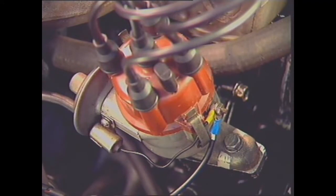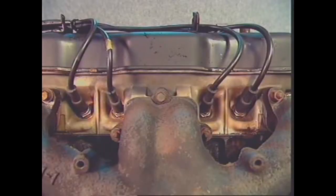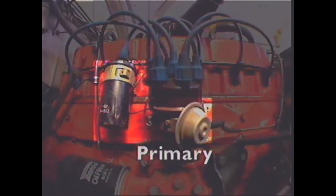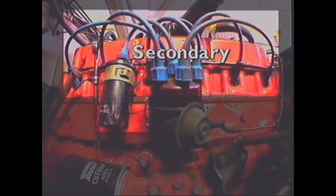a distributor, to house the contact breaker and distribute the high-tension voltage from the ignition coil to the spark plugs to ignite the air-fuel mixture in each cylinder in the correct firing order; and connecting wires and leads suitable for conducting the current flowing in the system at the appropriate voltage level. When these components are connected together, they form two distinct circuits, primary and secondary.